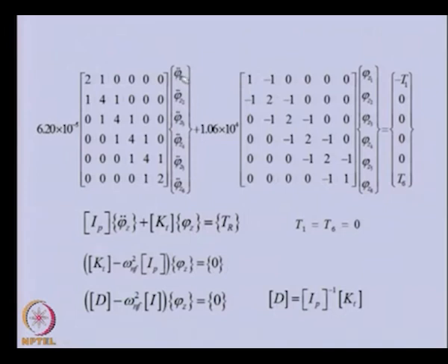And here you can see all the nodes; 6 nodes were there. So we will have field variables corresponding to all 6 nodes. And in the assembly, as we discussed, the first 2 by 2 block is for the first element, and the remaining will have the second element, third element, fourth element and fifth element. And the form of this equation is this. This is the mass matrix, inertia, this is stiffness, and this is the reaction torque.